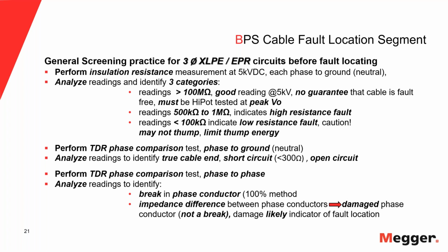They will find those, or they will indicate that I have that type of fault. But if I have an open conductor, there is one other test that we will do in a moment that will close the loop. With that test result in, I can make a final decision whether a cable is good or not. So it is several steps involved.